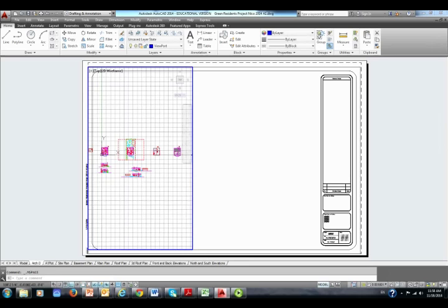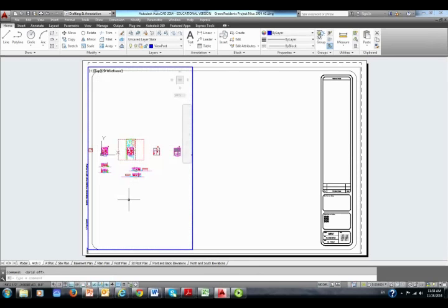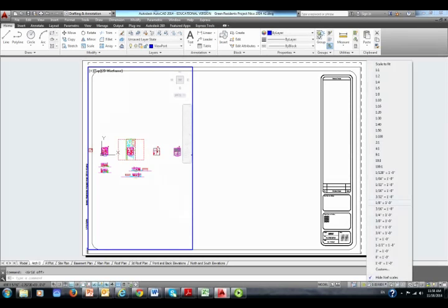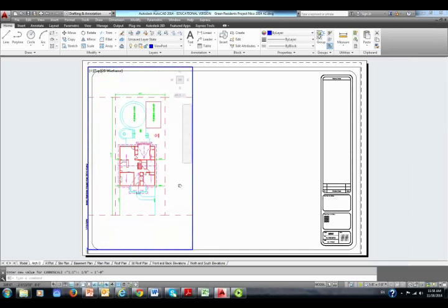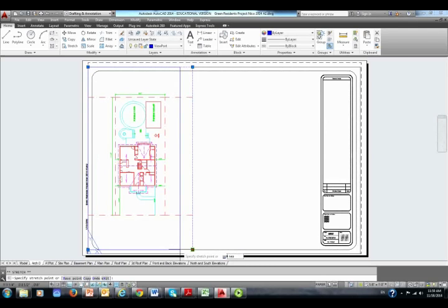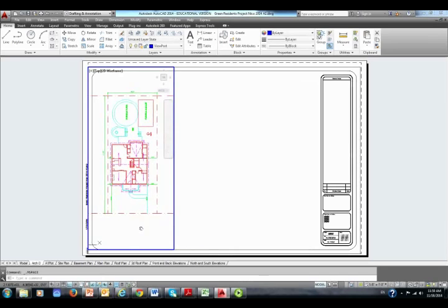Go inside again, turn grid off, and change the scale to, let's see what we can do. Let's see, 1/8 of an inch. 1/8 of an inch looks good, and I have a little bit of space, so I could make that viewport smaller. So maybe here I'll do 2 side elevations. Good. Okay, paper space. I could potentially simply drag this to near, maybe like so. Go back inside, pan a bit, and I'm happy, so I'm going to save.